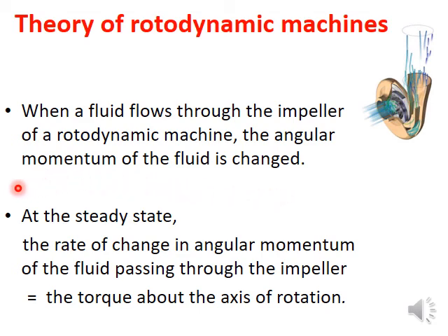But before we stop, you need to know this concept that we use to derive the power transfer. That is, at steady state, the rate of change in angular momentum of the fluid passing through the impeller is equivalent to the torque about the axis of rotation. And you have learned this under the application of conservation laws to control volumes in previous classes,